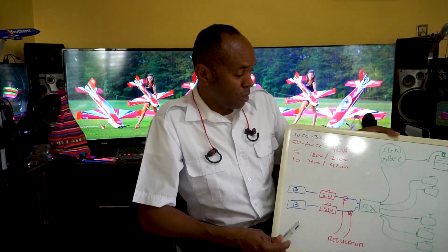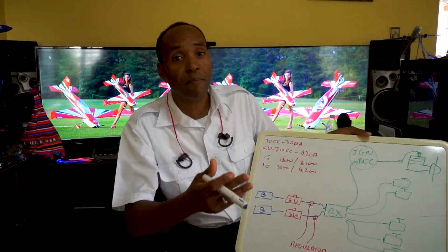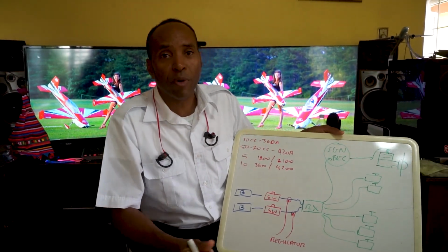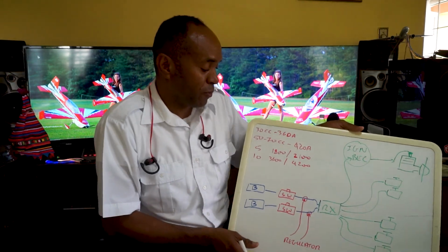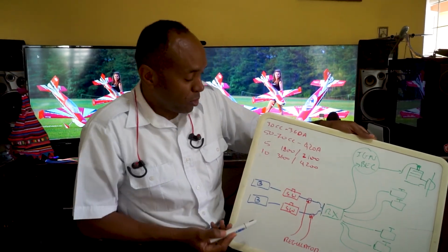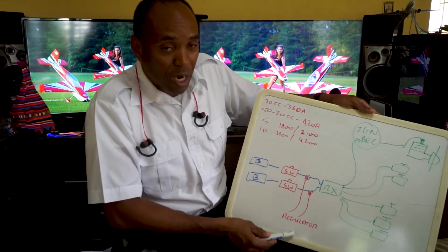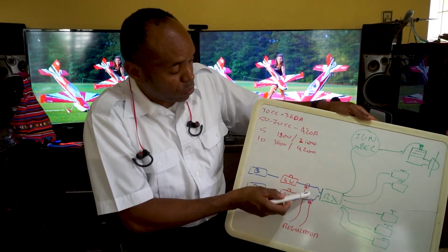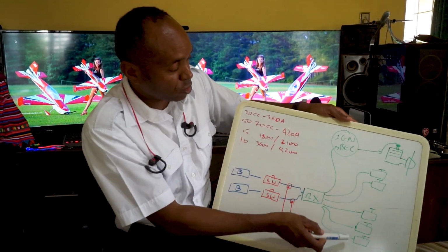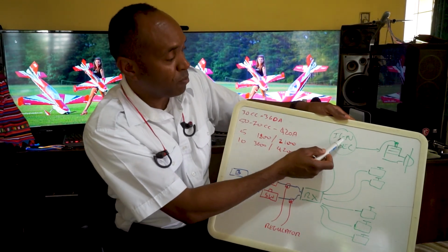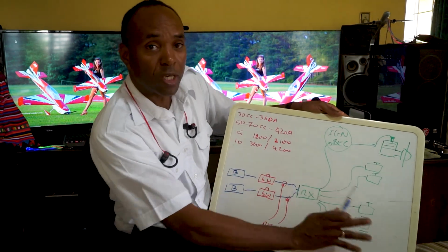So now, here is a simple schematic of your electrical system in a basic gasoline powered model airplane, whether 20cc, 30cc, 50cc, whatever. So this is a 2 battery setup. So you have 2 batteries, 2 switches. If you have a regulator on the system, you put it between the switch and the receiver. Here is the receiver. Here are your servos and your ignition BEC and your engine ignition. Right? That's the basic schematic.